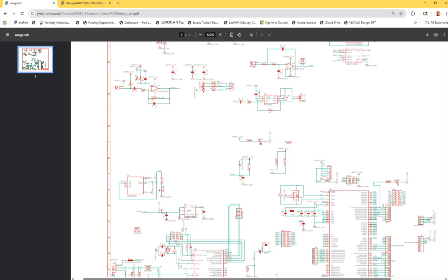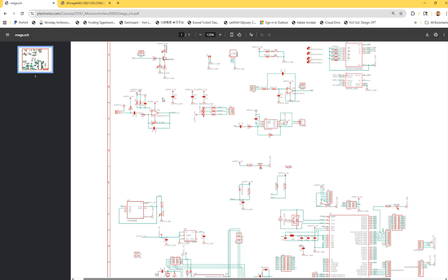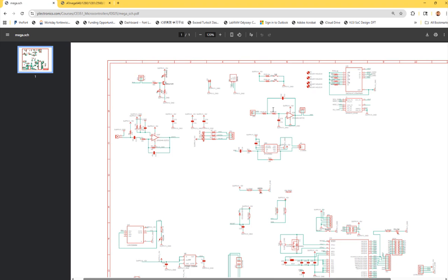Remember, you have to integrate two different modules from the Skyboard. We have the microphone, we have RGB, we have the audio amplifier, and we have this low pass filter being used for the DDS. That's another really important technique you guys should know actually. We're just running out of time, so I don't think we can still do it. It's using different frequencies to generate analog signals, like the general function generators in the lab. How do they generate all these analog signals? They use DDS, direct digital synthesis, and this is being used for quantum computer interfaces as well recently. So it's a really important technique to learn. If you get into some of the national labs and they ask you to generate different waveforms just using FPGAs, that's the technique you want to use.